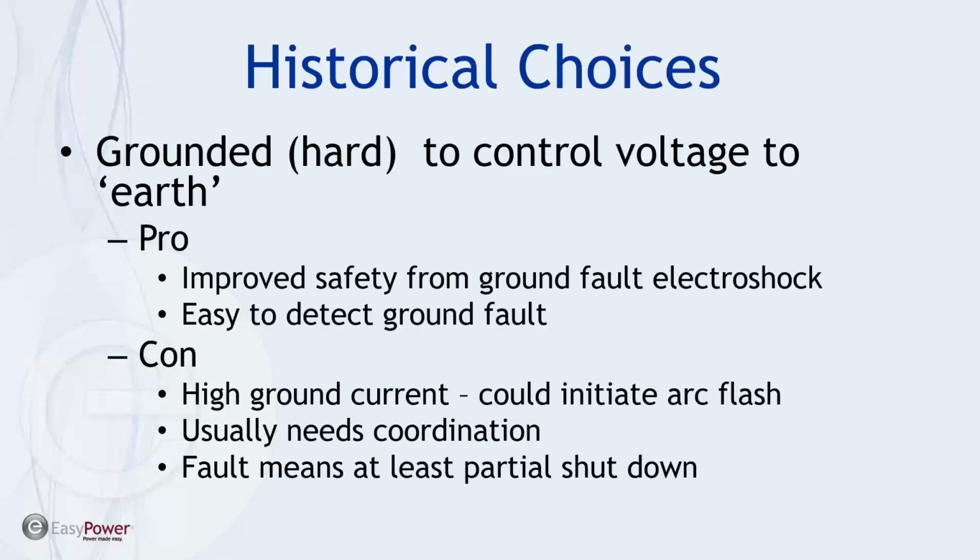Okay, historically, the choices to do grounding or ungrounding have gone back and forth a little bit like a pendulum, and so what might be the recommendation today may not be what was common wisdom 20 years ago. But historically, hard grounded systems improve the safety as far as ground fault and preventing electroshock.